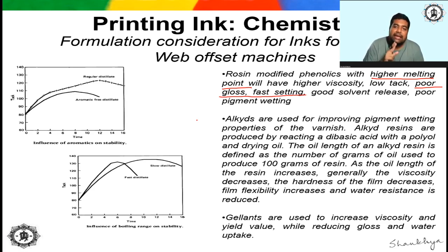Conversely, a varnish which is offering faster setting times cannot be used for preparation of an ink whose requirement is to provide good gloss. Why is this the case, you may ask. See, gloss is how much you are able to hold out the liquid component of the ink, or the distillate component of the ink, on the surface of the paper,